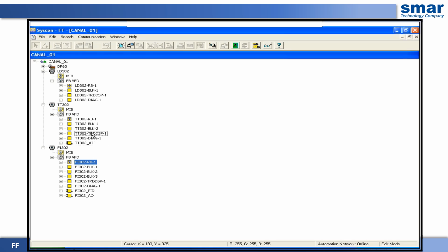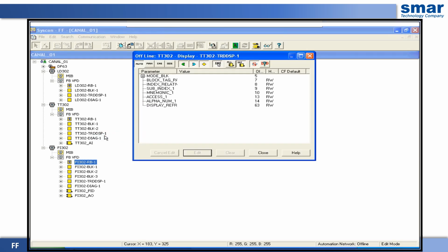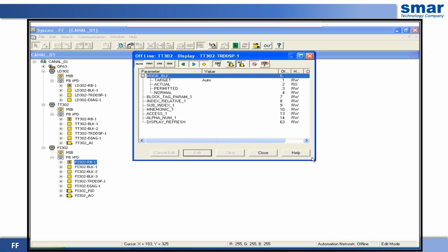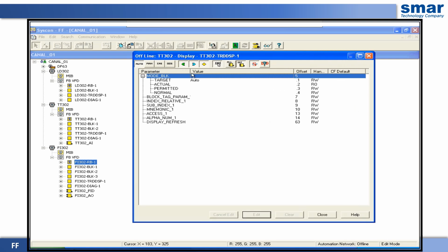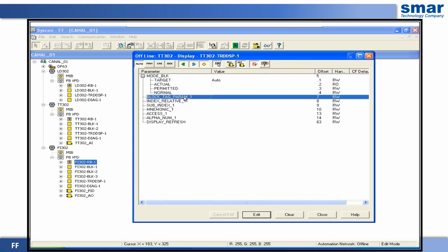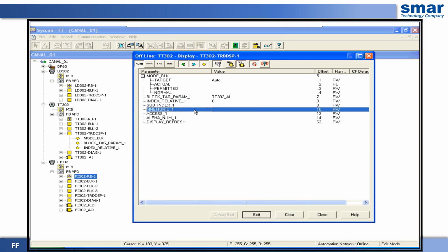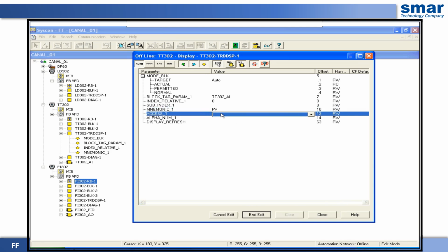Let's access the Attributes option. In Attributes, we can adjust our tag if required. We can apply this to any block. Let's enter the TT. We enter the transducer. In the transducer, we can make a setting to display, visualize our temperature signal. We configure the tag we want to see.